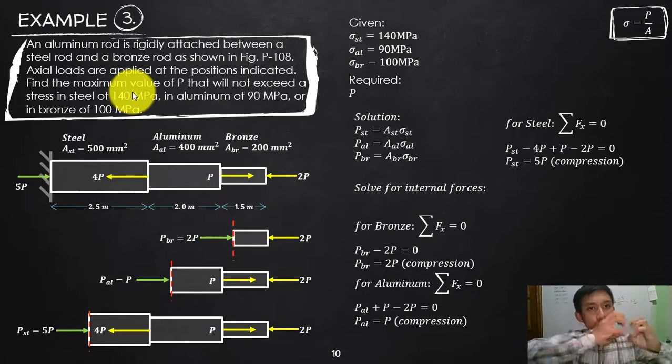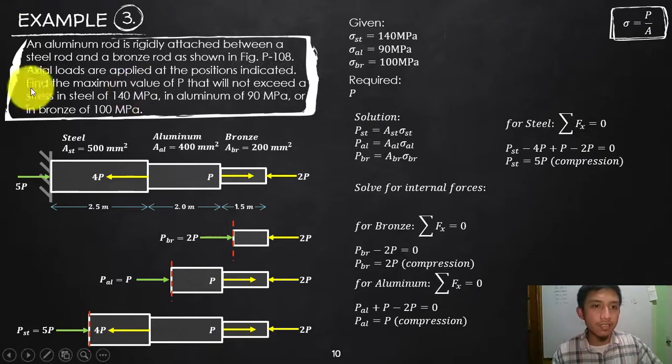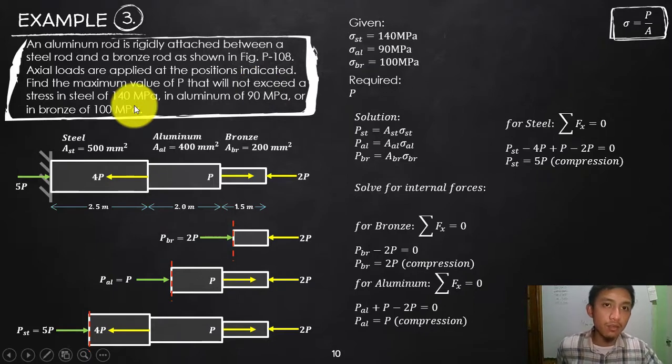But when it comes to tension, that will easily rupture. So again, concrete is weak in tension but strong in compression. So there should be different strengths within compression and within tension. However, since only a single strength is given for the material, let's assume that the compression strength and the tension strength are the same.